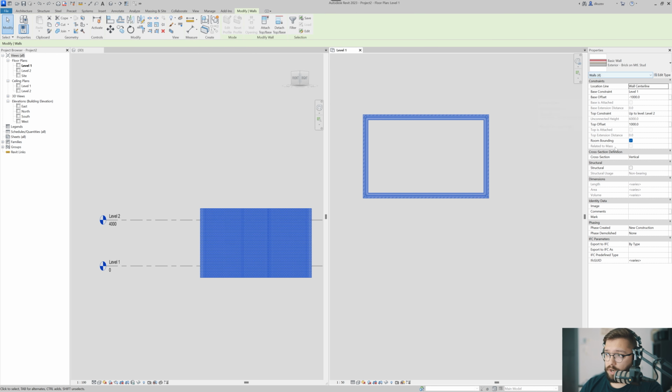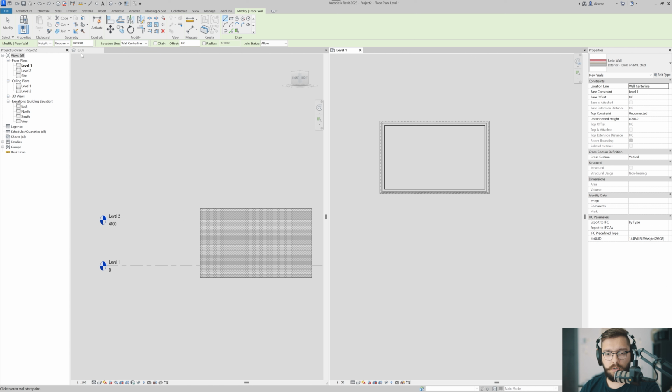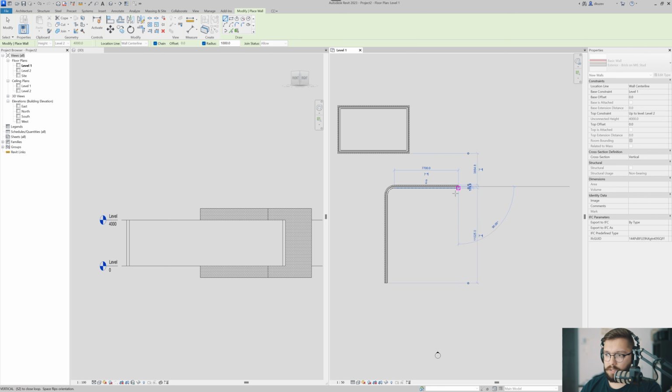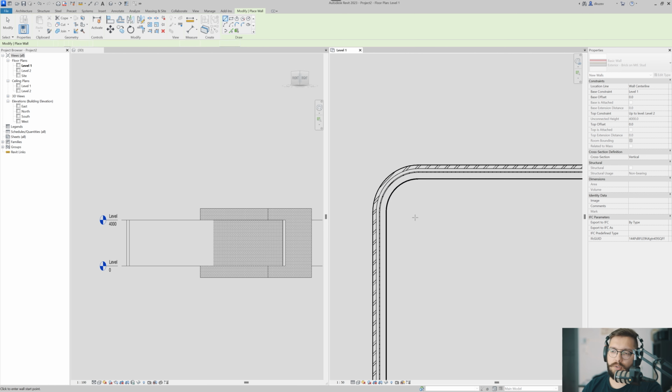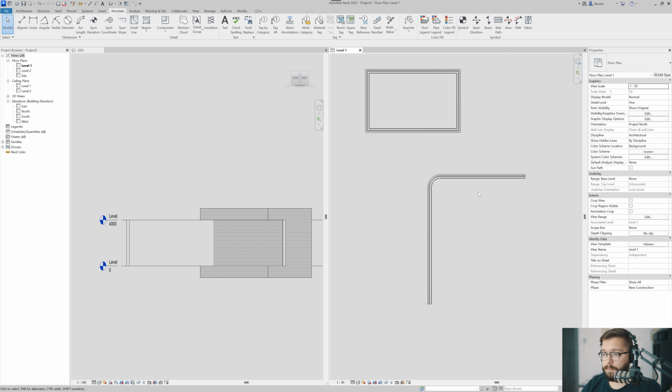These settings that we're looking at here inside the properties are actually available to you within the creation of a wall. So if I do WA again, and if I look here at my ribbon, I can already say, hey, I want this to be a height. I want it to be up to Level 2, and I want to chain it because I'm going to be creating several of them. My location line coming in a second. And if I have any particular offsets or radius. Radius is a funny one because I can create a corner and it would round it for me in this way. So if this is your cup of tea, you can do it right away while you are drawing, okay?